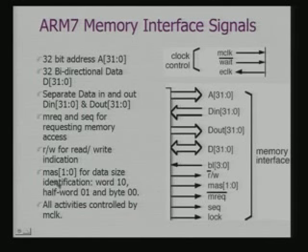This one we will look at, the size. If you remember, we started the basic model where we had size as a signal. So, this is a 2-bit signal because it indicates the different sizes. So, this indicates the size of the data which is to be transferred over the bus. And all these activities are to be synchronized with regard to the MCLK, that is the system clock.